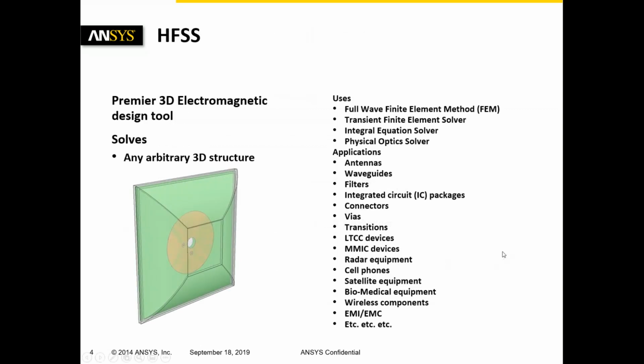HFSS is a premier 3D electromagnetic design tool that solves any arbitrary 3D structure. There are multiple solvers in the software. The flagship solver is the full wave finite element method, that's FEM. It also has a transient finite element solver, as well as an integral equation, aka IE, solver, and also a physical optics solver.